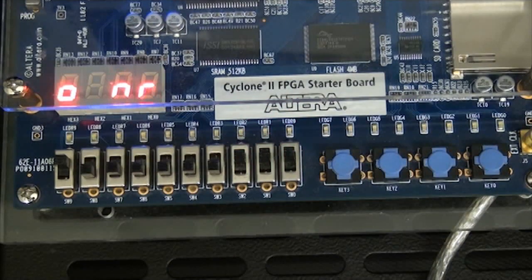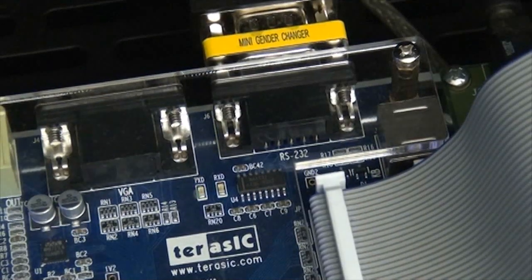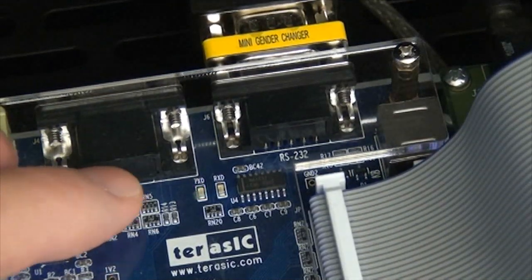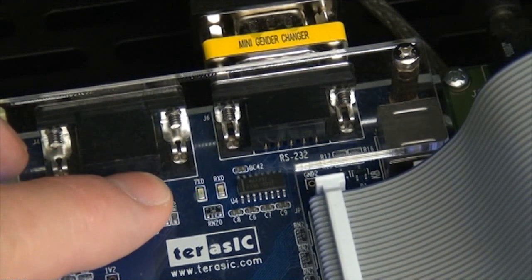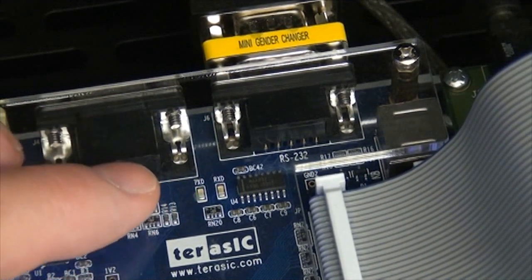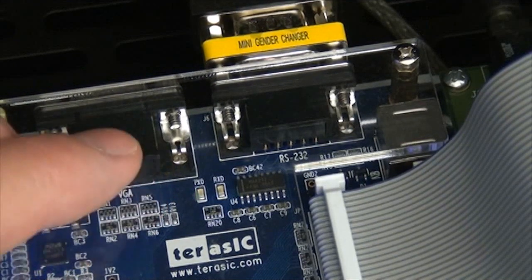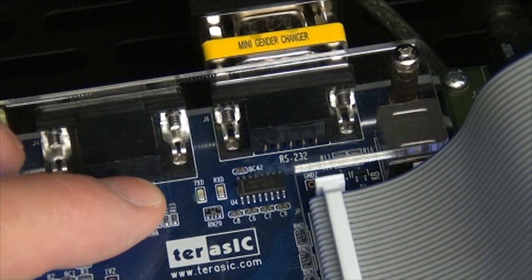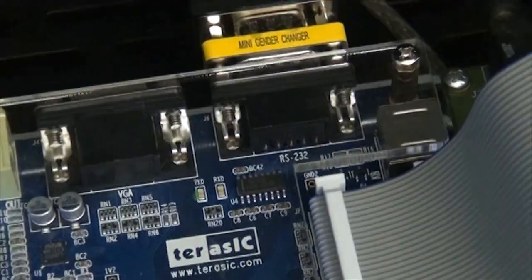Next, let's take a look at the communication between the two boards. Now, one of the checkpoints that you have in your project is that you can be transmitting. This is the monitoring station here. The green TX LED should be flashing, indicating that periodically you're sending information. Now, as it shows in the project documentation, there's going to be 2 bytes sent. And of those 2 bytes being sent, one will have an MSB of 0, one will have an MSB of 1.